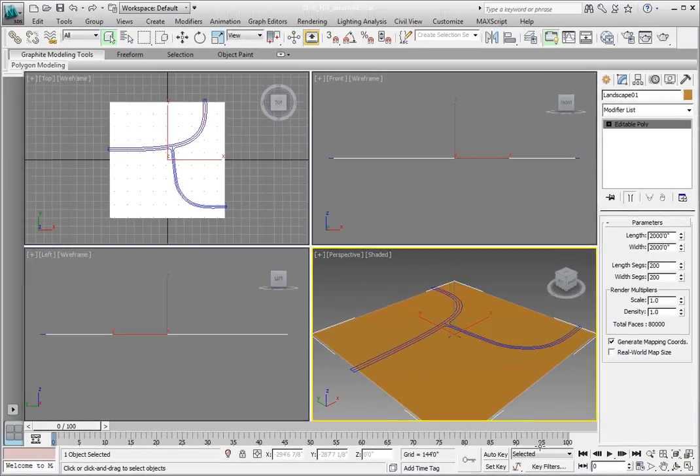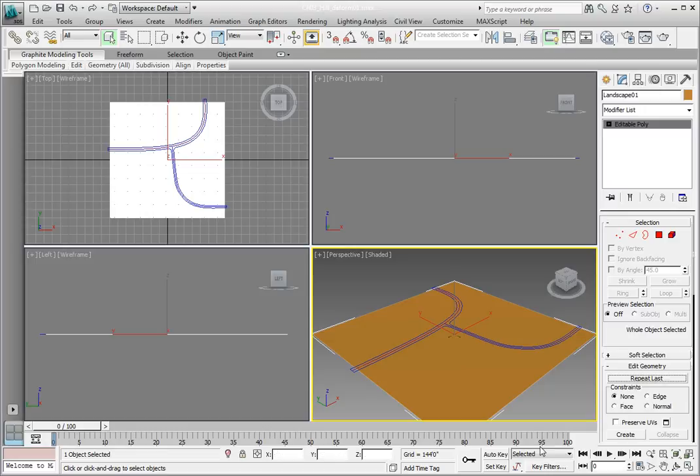We're now able to work at the sub-object level, and we have a new set of editing tools available to us. We're going to go ahead and change our selection method so that we can use a tool later on in our editing process. In the main toolbar, make sure you're in Select Object mode. Currently, we're selecting our object using a rectangular selection region. Click and hold on the rectangular selection region, and all the way down at the bottom of the flyout, you'll see a spray can. This option allows us to select by painting. This selection method is an alternative method we can use to edit our geometry. Release the mouse button to make the change.